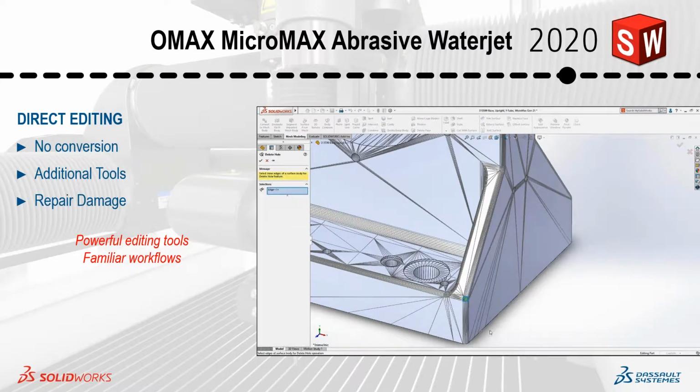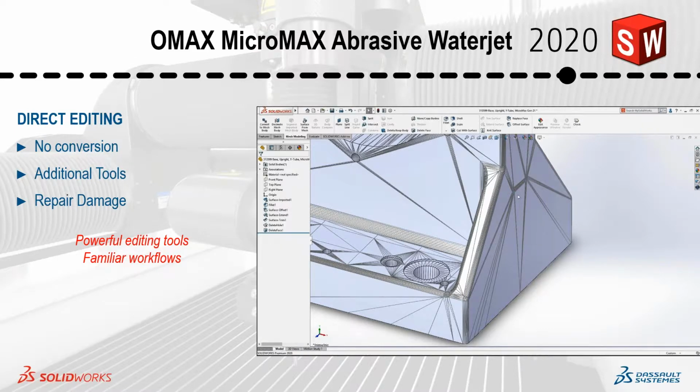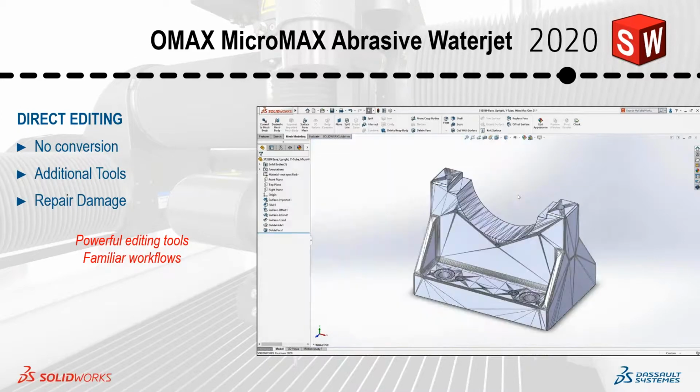We can immediately delete those holes or open surfaces. At the same time, in SolidWorks 2020, we even have a delete and fill feature. So instead of just removing the feature, we're filling it so that we no longer have that particular feature inside that mesh geometry. So moving on.